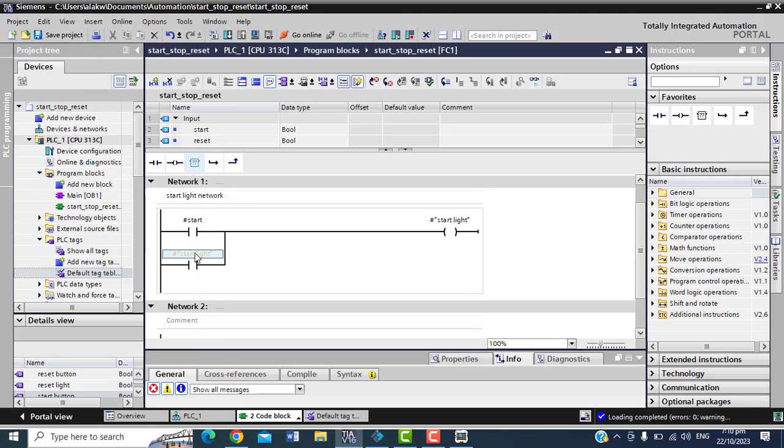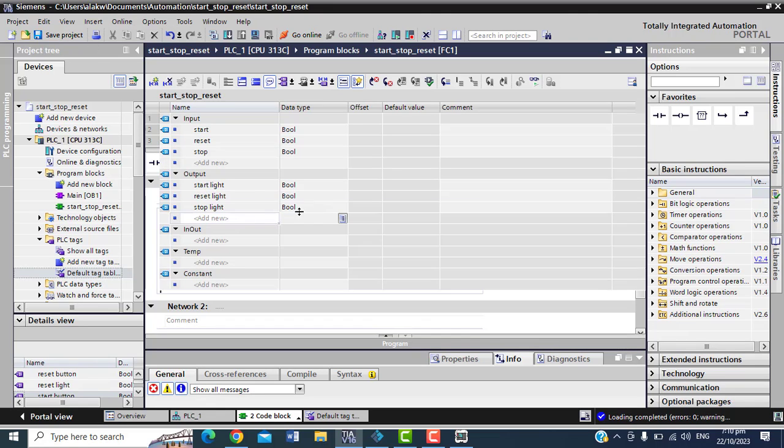And actually some of you are wondering why this yellow light, the yellow color there. It is because, what's the name? I declared this thing as output, but now I go and use the name also as an input. So it gives me a warning. This is what I declared as output here, you still don't use it as input. Now make you get something like in out.